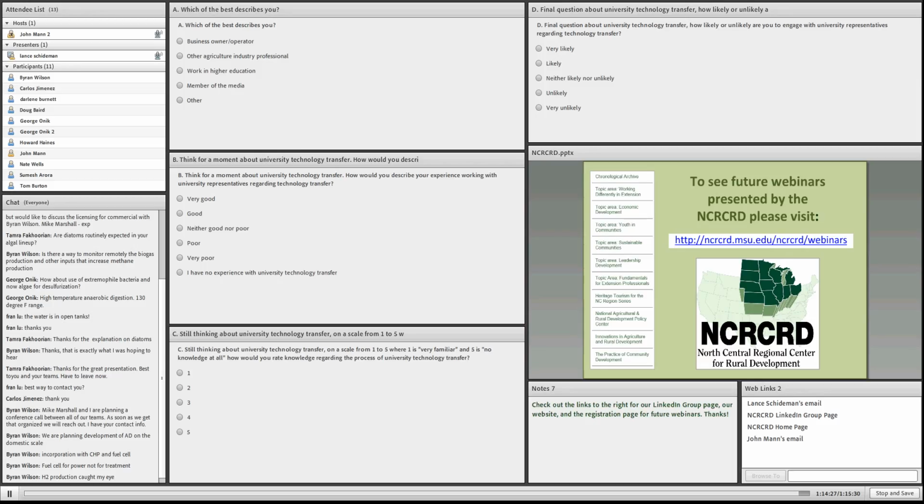And then of course there is hydrogen production as a part of anaerobic digestion as well, although it's a small component and it's usually quickly eaten up by the microbes. And finally, the process I mentioned, catalytic hydrothermal gasification, makes a syngas that is largely hydrogen-based. That would be very much like hydrothermal liquefaction, but instead of making oil, you're making a syngas product, so that would be another way to get some hydrogen out.